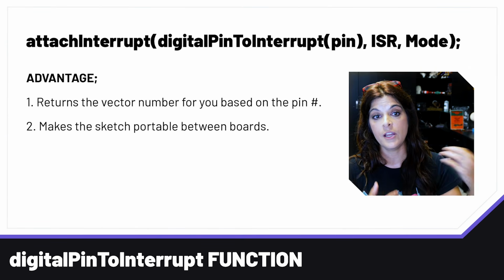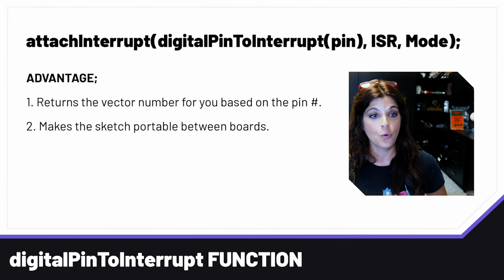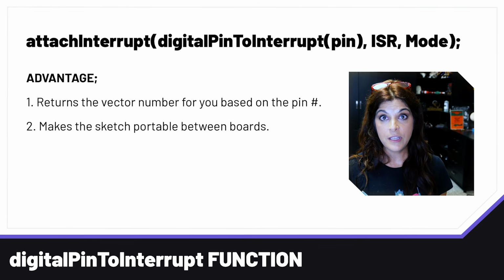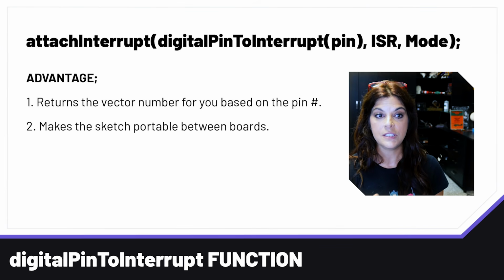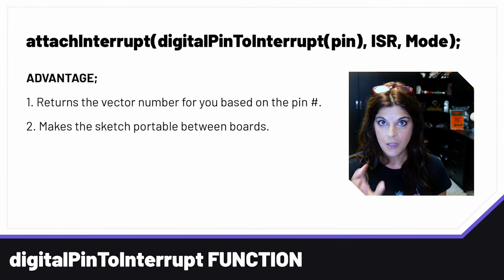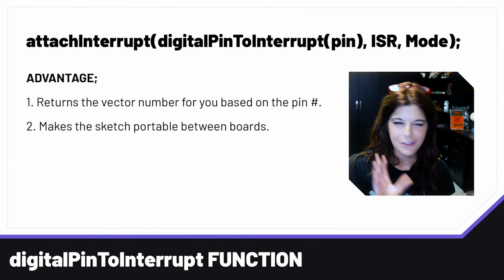You have your interrupt service routine and your mode. So those are the advantages of, instead of putting your vector number in there, using the digitalPinToInterrupt function within a function, basically.